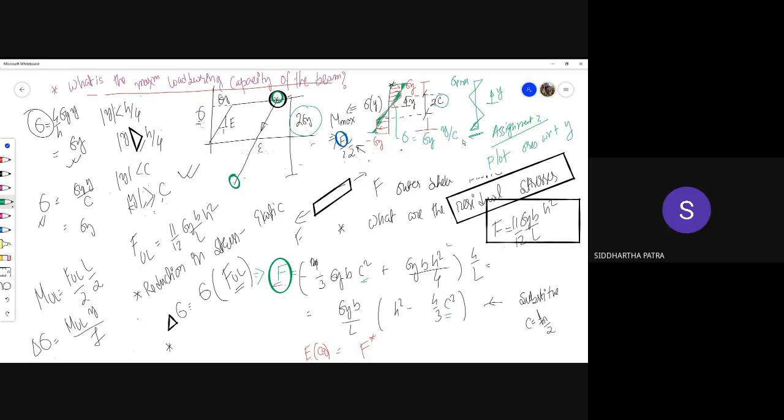So having that compressive state frozen in the weldment, how does that help? When you load the welded joint, and in some place a tensile stress state develops, then it has to go from a negative value first to zero and then to the tensile side, thereby reducing the chances of failure.